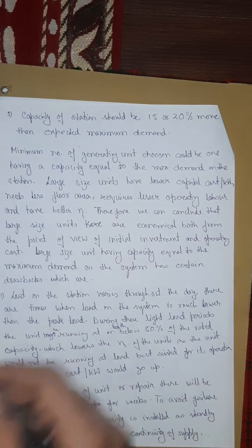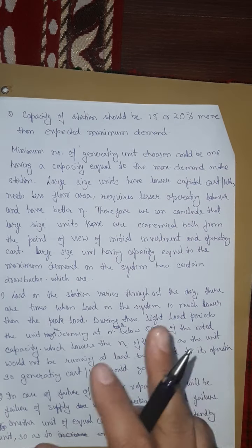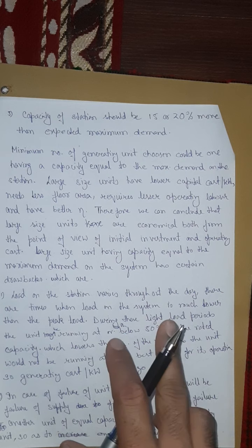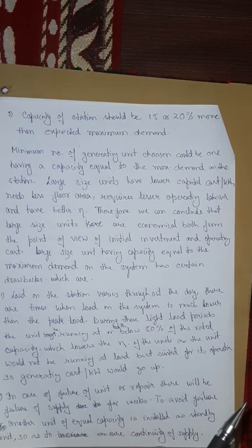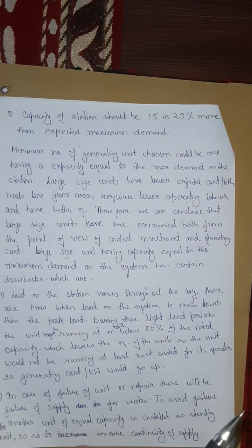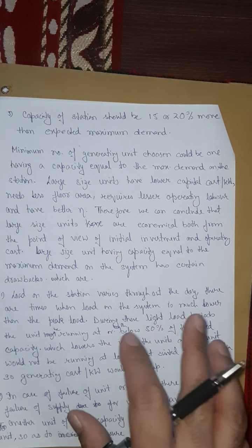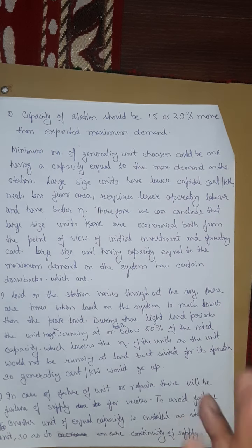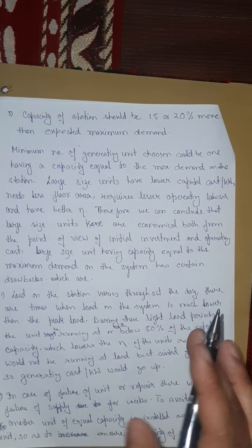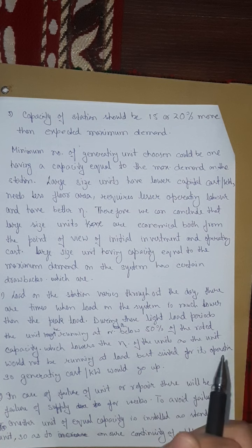So therefore we can conclude that large size units are economical both from the point of view of initial investment and operating cost. If we are using large size generators, the initial investment will be low, and moreover the operating cost will also be low. But using a single generator of large capacity equal to the maximum demand will have certain drawbacks.